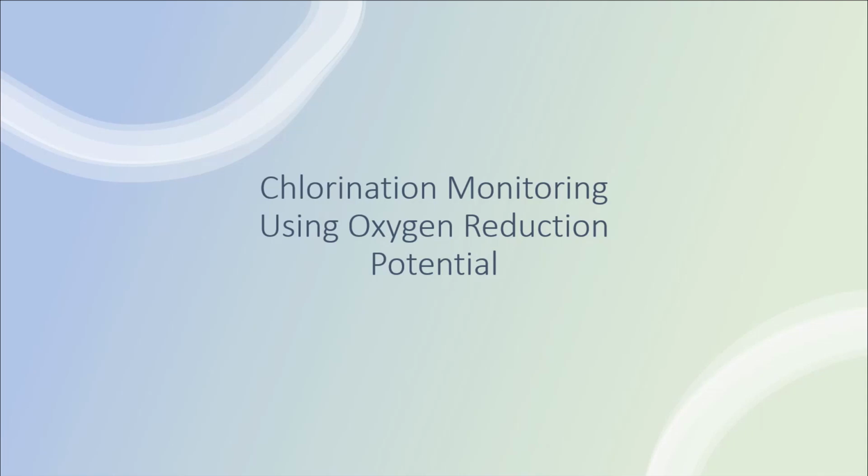Yeah, this is a great thing. Just with the city of Pendleton, I think there's about 5 or 6 different chlorine monitoring systems that we've tested out over the years, and there's either a ton of maintenance or chemicals involved in the system, or they just weren't accurate. And then we've continually fallen back to the ORP probes.